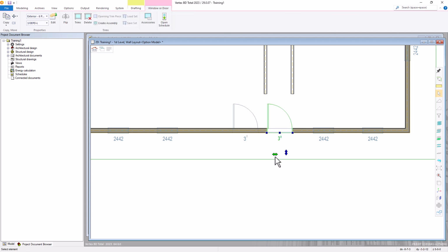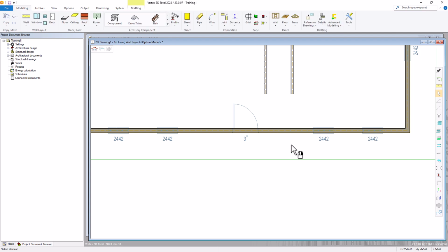You can also change the side of the door, so you can mirror it by using the left and right arrowhead. And then you can flip it using the up and down arrows. You can edit the door and fix it if you incorrectly placed it without having to delete the door and reinsert it. I'm going to select that door and select the delete key to remove it.